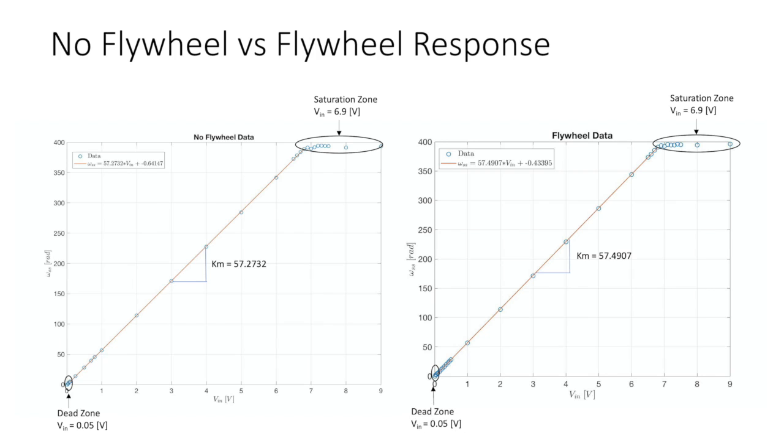Aside from the time motor constant, the motor gain, or Km constant, is also a pivotal parameter in characterizing a DC motor. This parameter is important because the motor gain shows an individual how much input voltage is needed to reach a certain angular speed or position. Creating a graph of input voltage versus a series of steady-state angular velocities previously experimentally determined, Km is found to be the slope of the linear portion of the graph.